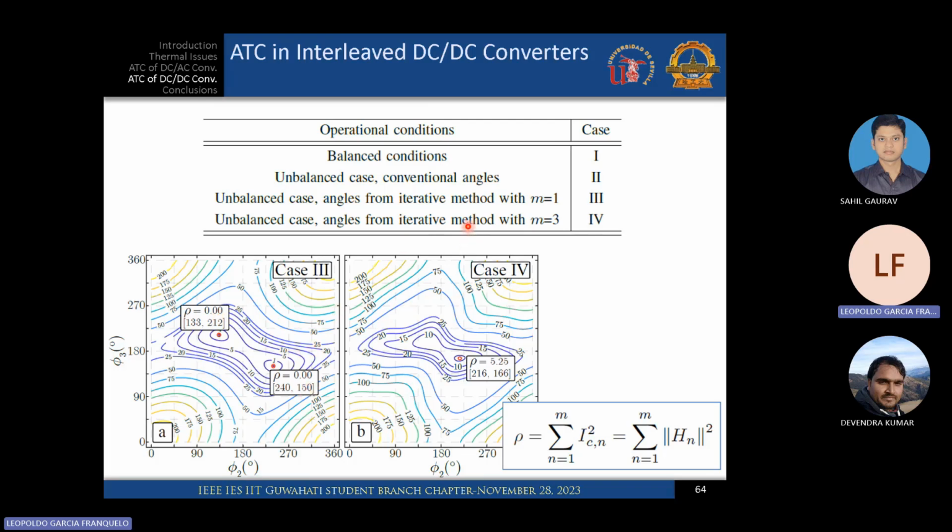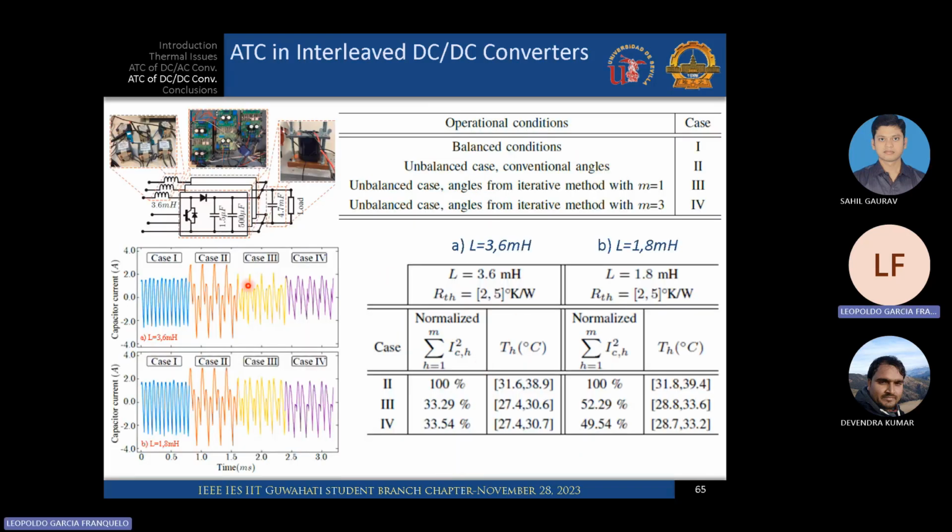In the case where we are trying to minimize the harmonics, or make zero or the minimum in 3 groups, we work with all the frequencies up to 3 times the fundamental frequency of the carrier. Then we have a solution that is not zero, but is small enough to consider it interesting, with these angles instead of 120, 166, and so on. Okay, then we can show this and the result.